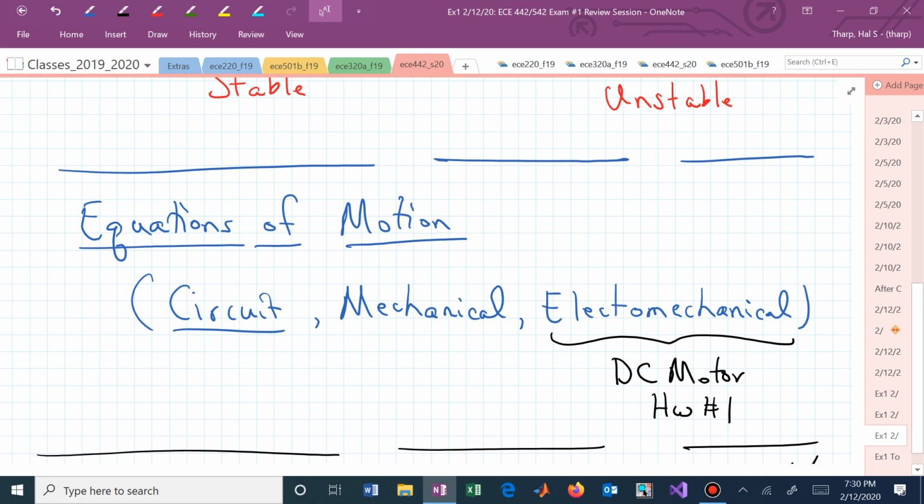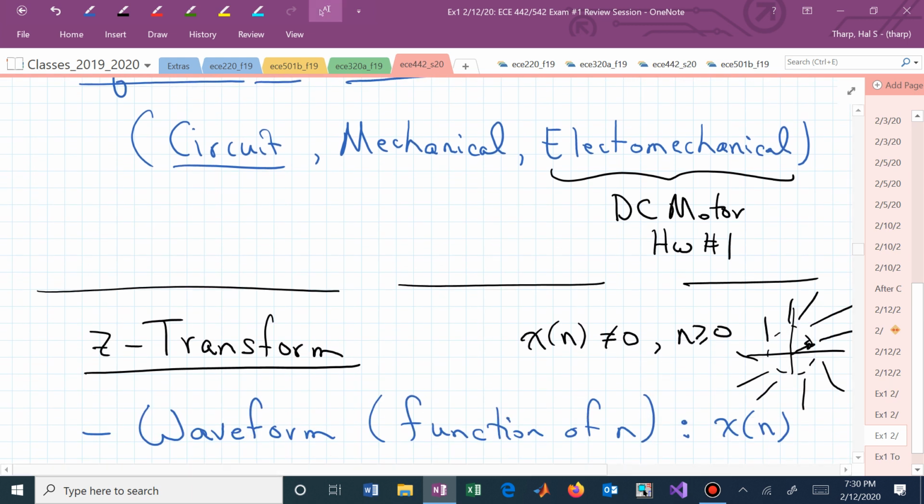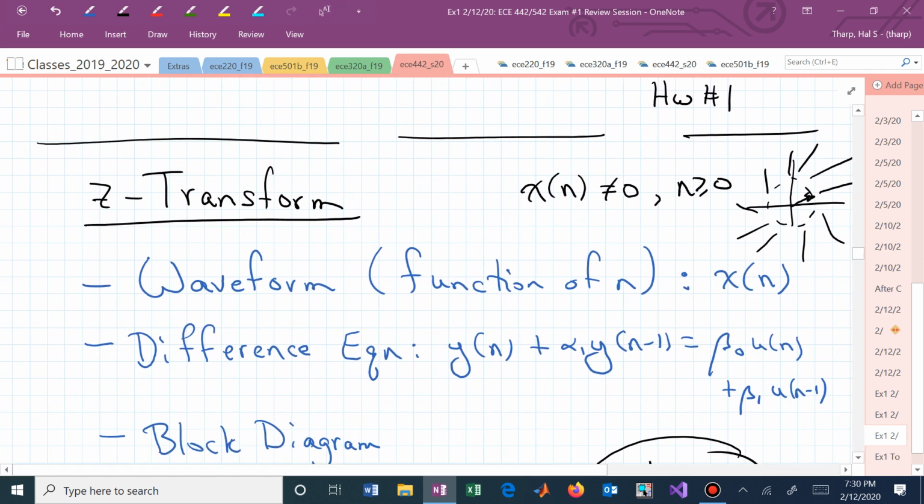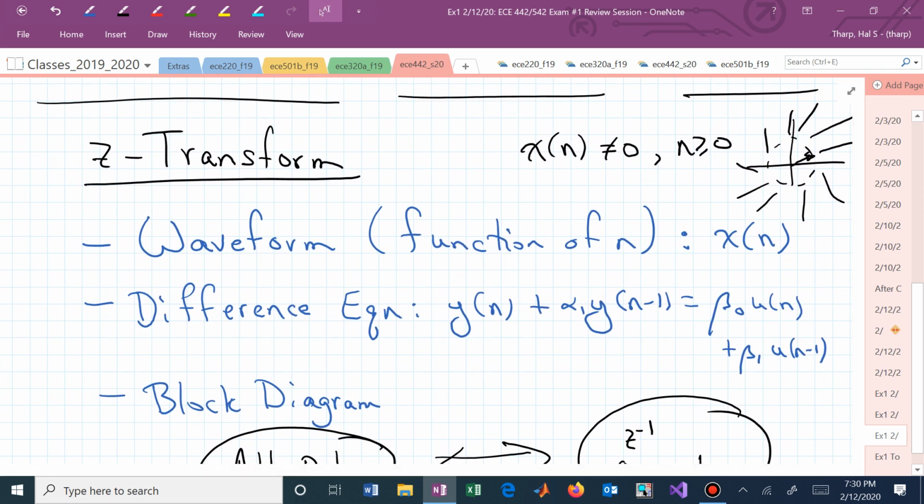Now you know what to do. You would plot those and say which one is the furthest to the left half plane. That's now my omega c. I sample 30 times that. That's my omega sub s. If I need to know capital T, I can find that by 2 pi over capital T. And I don't think you're going to have time to take a circuit and, well, yeah.